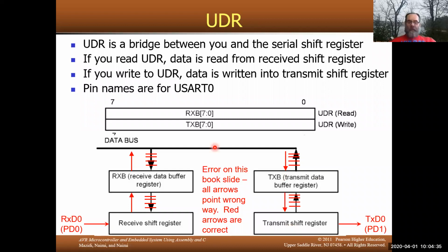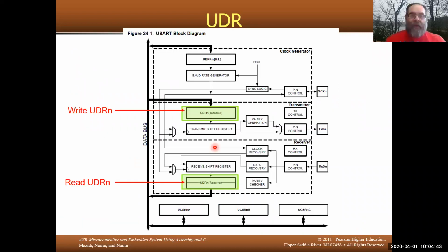All right, there is a lot of stuff in here that's not really important to remember, but when you write to the UDR register, again, writing UDR 0 has a different set of bits that are read from than are written to. So I write to the register, eventually it gets shifted into the shift register. There's all kinds of parity that can get generated.